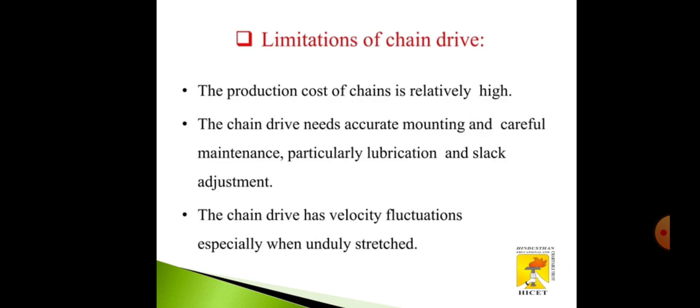Some of the limitations: the production cost of chain is relatively high, and it needs accurate mounting and careful maintenance, particularly lubrication and slack adjustment. The next one is velocity fluctuations, especially when unduly stretched.